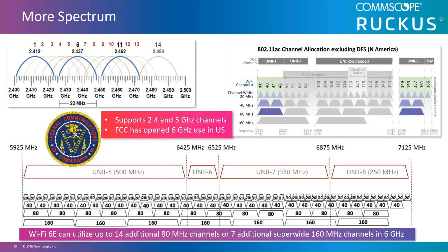The end result of the 6 GHz process in the US is that it opened up 1200 MHz for Wi-Fi. The amount of band available for Wi-Fi in the US has remained unchanged for more than a decade. The confluence of the new 802.11ax and the new 6 GHz spectrum may just fuel a wireless industry perfect storm of disruption. Also, for the channel bandwidth in the 6 GHz band opened up, 160 MHz could become reality, and 11ax is compatible with earlier 802.11 standards.